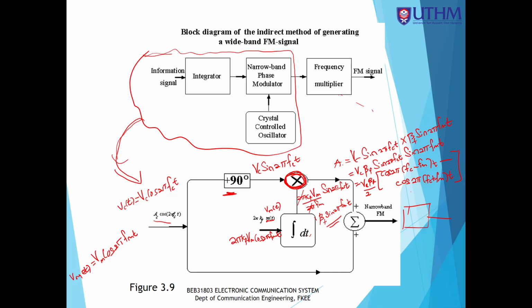So sine and sine will produce an upper sideband and also the lower sideband. And then down here, Vc is supplied here, Vc cos 2 pi Fc t. So this is at point B, for example. And then at point C, we need to add A and B. At point C, it is A plus B.